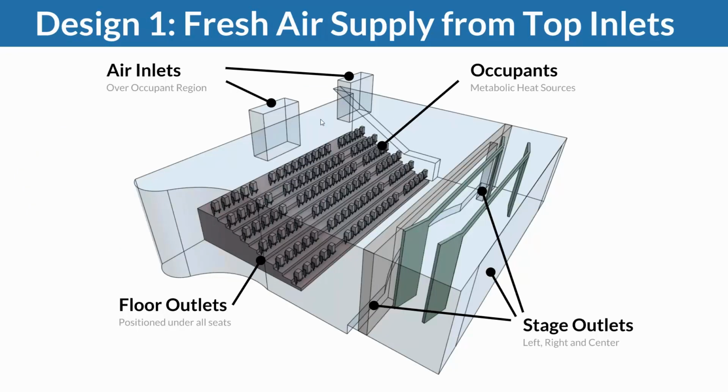What we're doing in here, just to look in more detail at the design, we're looking at this and saying, okay, based on our experience and how we would typically design the system without simulation, we're using a mixed ventilation system. So we're bringing in air from the top over the occupants here. Obviously the occupants here on the right, let me quickly bring up my drawing tools. Okay, so we're bringing it in at the top and we're using a mixing ventilation system.